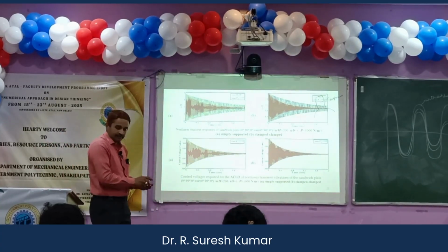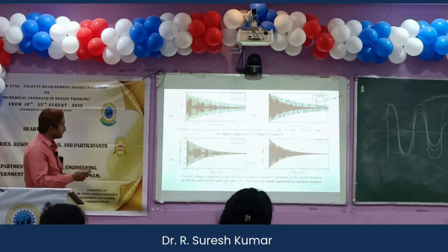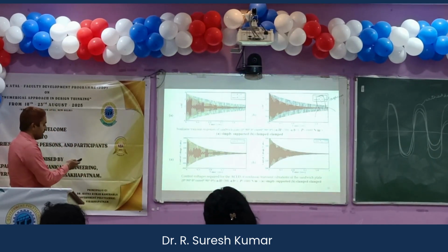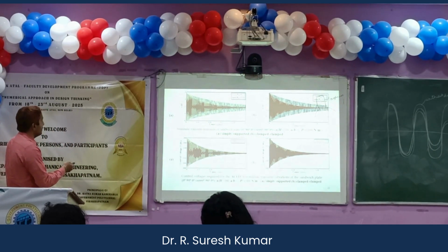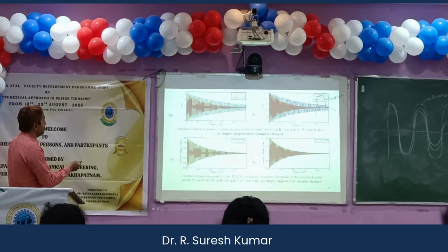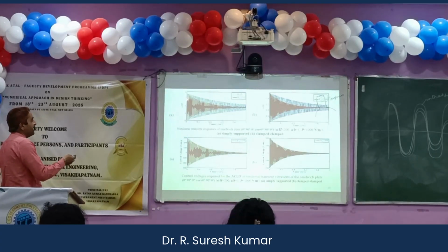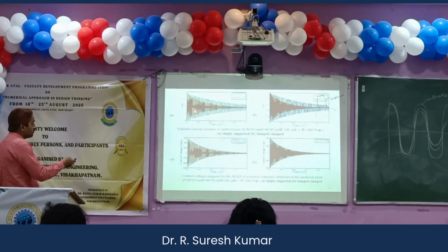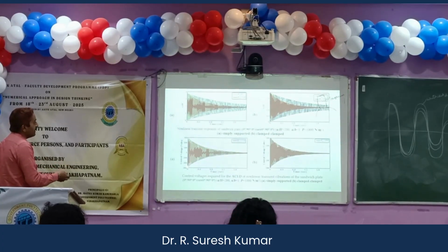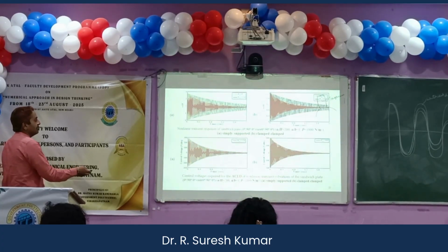So that's why you can clearly see it has reduced. So the first one, the blue one, is the passive damping, where control voltage is not given, and the red one is the damping or reduction in amplitude when control voltage is given. The corresponding control voltage for this is, so for getting the red one, the voltage that needs to be supplied to the system is like this.